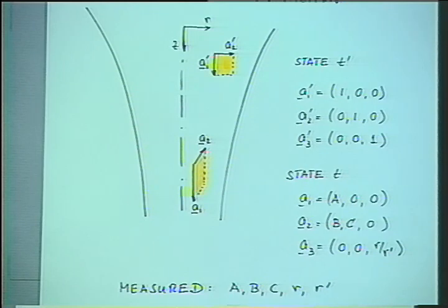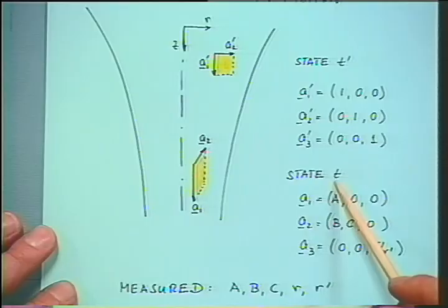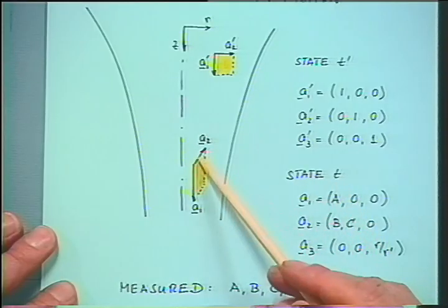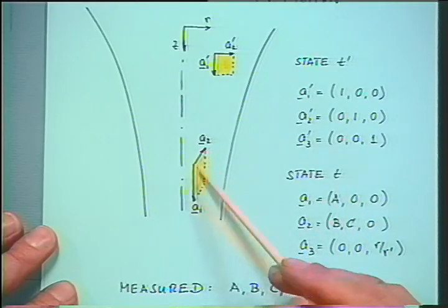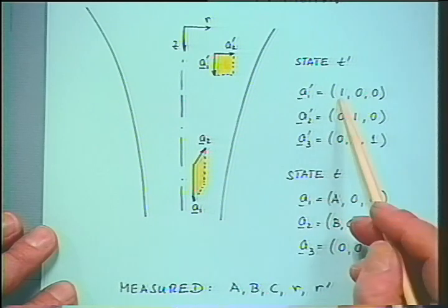The method of picking a material coordinate system at time t, which is orthonormal, doesn't work here. We are not free to choose that material coordinate system. We just get as much as we have available. We have, for instance, at some later time, the most distorted element. We have A1 and A2, and we can measure A1. We can measure its new length. Before it was, say, length 1.